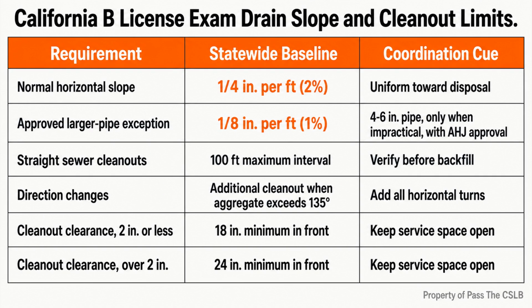The practical effect of the sleeve is separation. Concrete and piping can move differently as the building settles, temperatures change, and loads act on the structure. A sleeve or approved protective method prevents the penetration from being locked directly into the concrete. I do not need to invent a statewide sleeve thickness or a local material rule. The statewide coordination point is protection and separation in an approved manner.